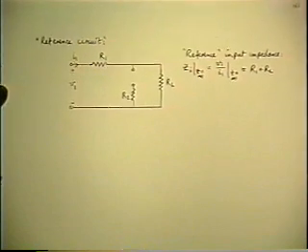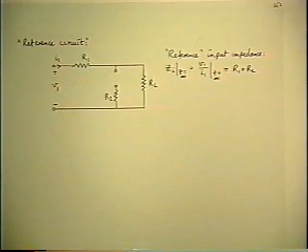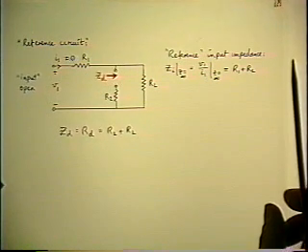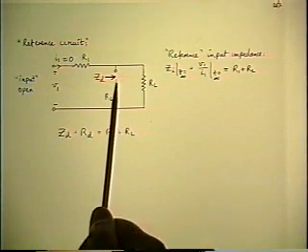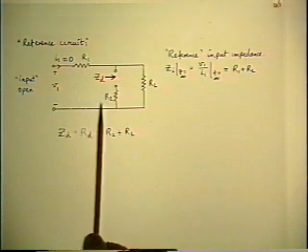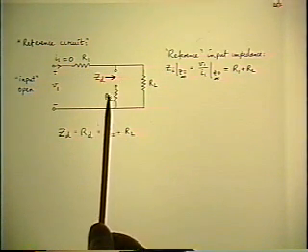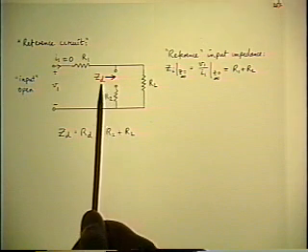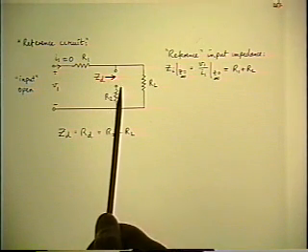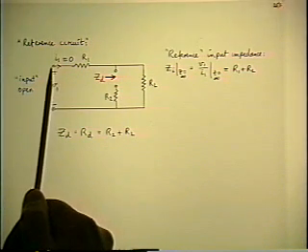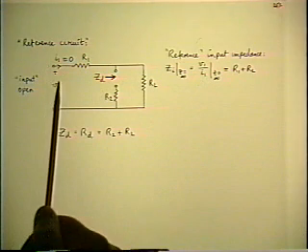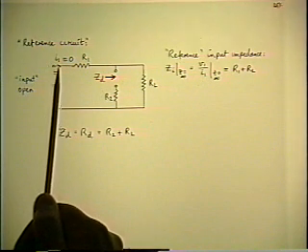Now we have to calculate the two driving point resistances at the position where the extra element is going to go, which is across this pair of terminals here. So we visualize the second source, which I'm not drawing, and we calculate ZD, or RD in this case, under conditions of open input. And because the transfer function is an input impedance, the input signal is I1.